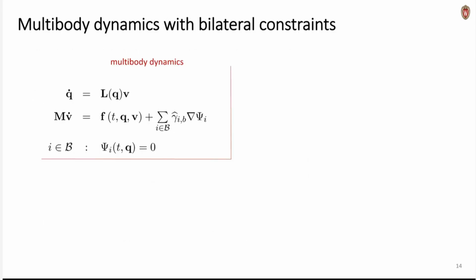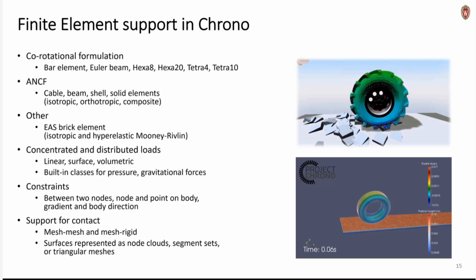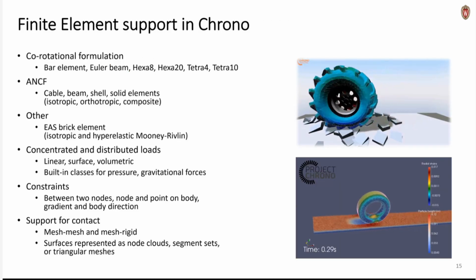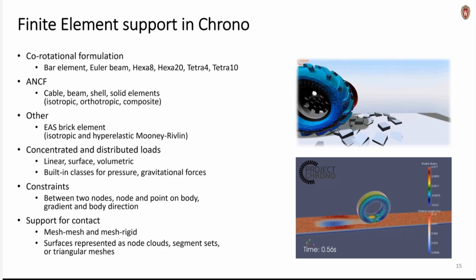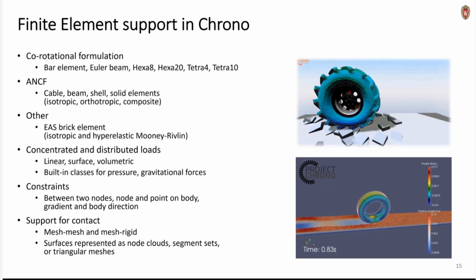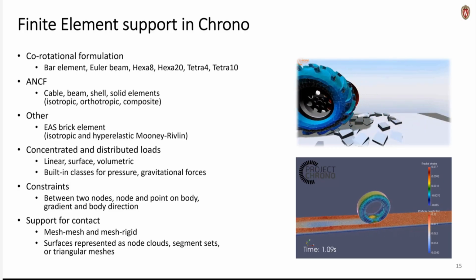So these are the equations that you have to solve for rigid multi-body dynamics. I'm pretty sure that you went through this. These are the index 3 DAEs of multi-body dynamics. And this is only the part of a set of equations that will be extended later when we add contact and friction.